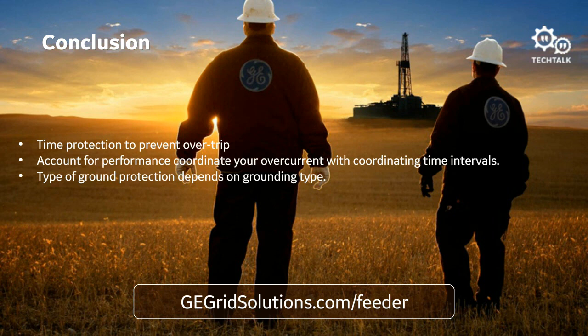Is the time delay setting used for the coordination between relays? Yes, so if we have definite time delay elements, so if we have an instantaneous element and we want to set it as a definite time delay, then yes, we could set that definite time delay to coordinate between other definite time delay elements. The other thing is if we have a time overcurrent curve, we can use the time dial setting to coordinate between devices.